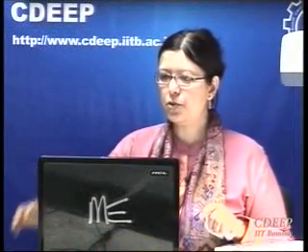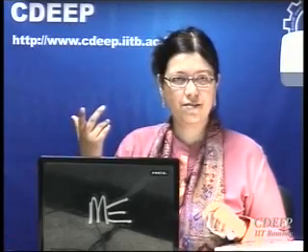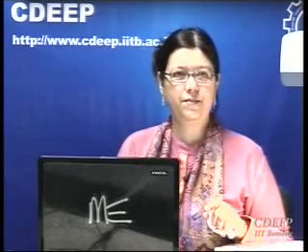Now at the output you use a very fast digital MUX, again operating at 2 Fs. Therefore practically you have achieved a 2 Fs sampling rate using ADCs which work at Fs. It is very similar to TDM in communication.